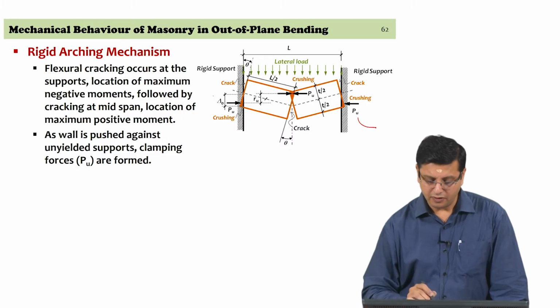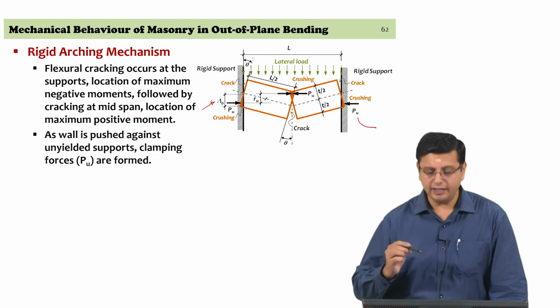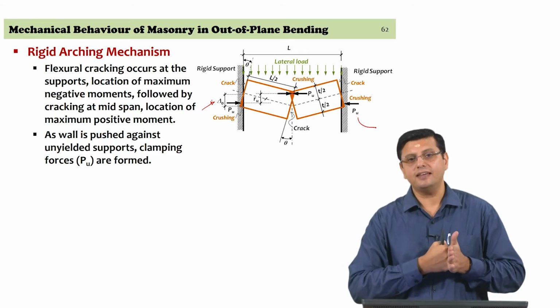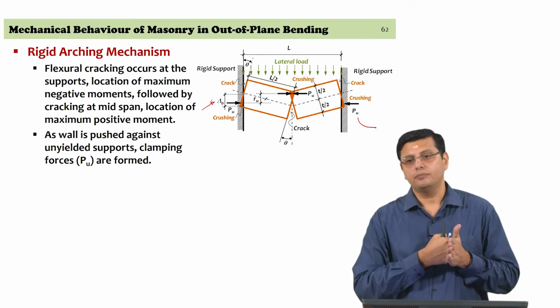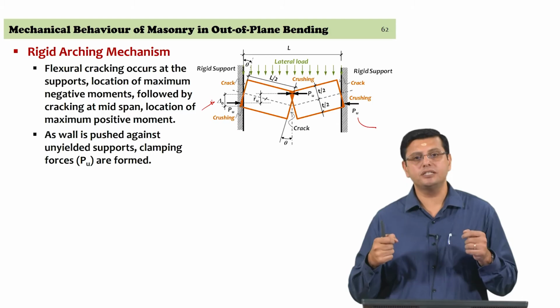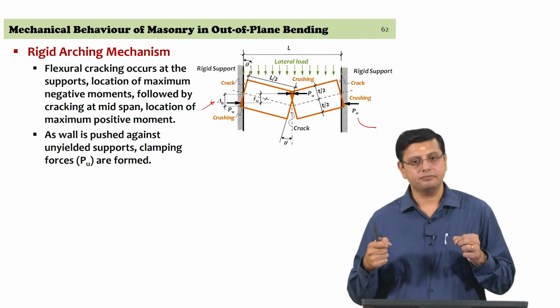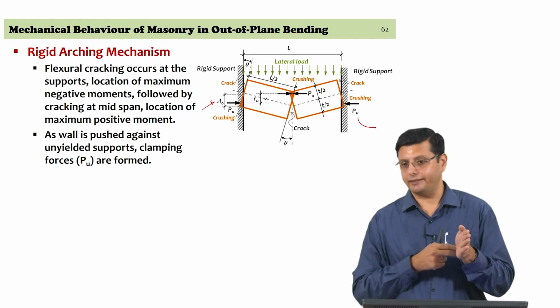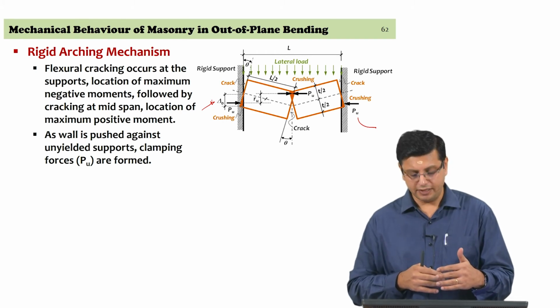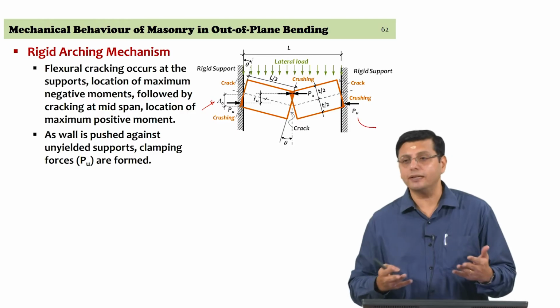You see the length of contact, and this length of contact is because the masonry, as the compression forces increase there, is slowly getting plastified. So, as that happens, the contact changes from being a point to a finite length, and that finite length is a delta naught that we are designating at this point in time. We will have to make some assumptions on how much that can be.